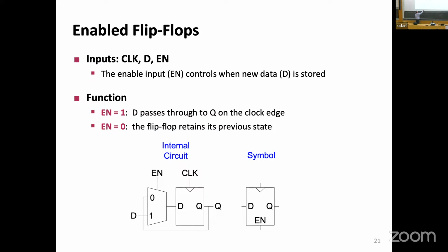So instead of not sending it the clock signal, we do the following. We say, hey, Frank likes multiplexers, let's put one here. The D will go through if there is an enable, otherwise I'll just give back what the output was and memorize it. Looks like a waste of time. It is a safer and nicer way of doing things. We call flip-flops that have this capability a flip-flop with an enable input, or an enable D-type rising edge triggered flip-flop. Okay.